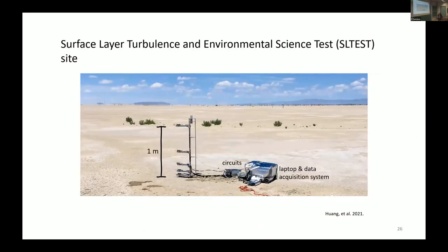All right, so now we're going to switch, because we did all this for supersonic measurements, but it turns out that it's really convenient in the atmospheric boundary layer. If you do field experiments, you might say you want to have 100 sensors somehow distributed in your boundary layer measurement. If you were to go to Dantec and say, give me a quote for 100 sensors, they would happily give you a quote, but it will be a couple of $100,000, if not more. And with constant current, you can build a circuit yourself. There's no feedback. It's very easy.